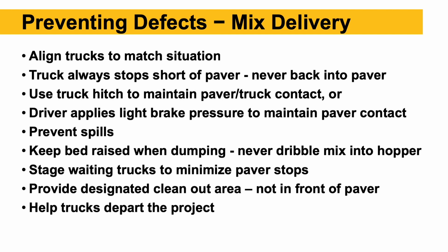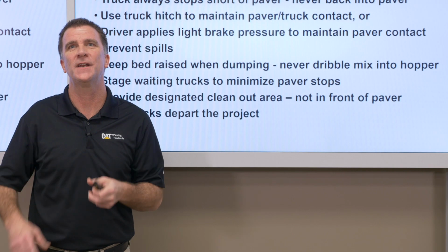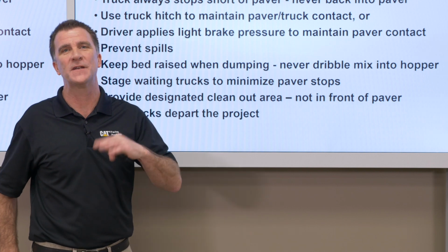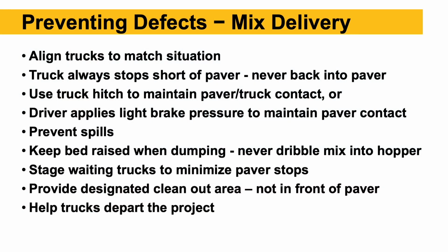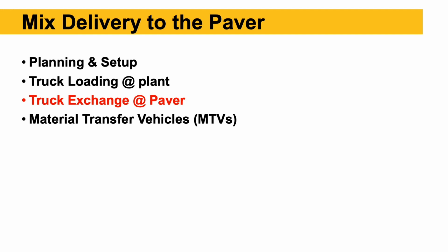Keep the bed raised when dumping, so we want to raise the bed fairly quickly and let a big mass of mix move into the hopper at one time. Try not to make small incremental raises in the truck bed where we're just dribbling mix into the hopper. Stage trucks so that we can minimize the length of time for any paver stops in between trucks. Provide a designated clean out area, not in front of the paver, somewhere off to the side. And maybe think about a traffic coordinator to help trucks get in and out in front of the paver, depending on traffic conditions. So that's some of the things with mixed delivery, the truck exchange.